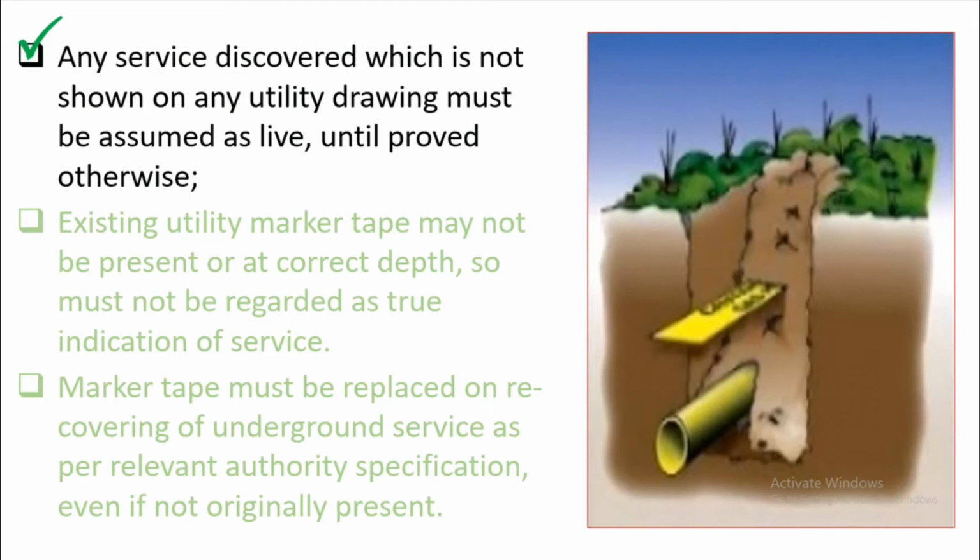So always coordinate with your MEP department or electrical department to check with the utility services that this cable is dead. Unless they confirm that this is dead, don't assume that it is dead. So always assume that the cable is live.